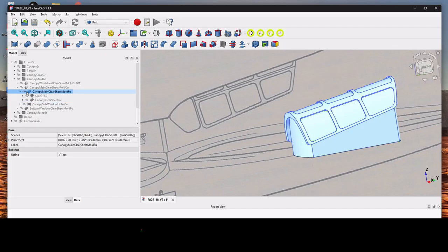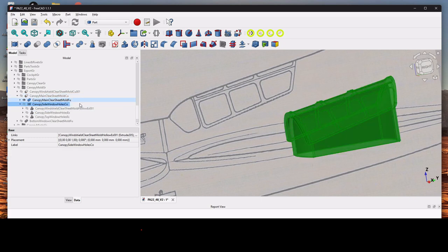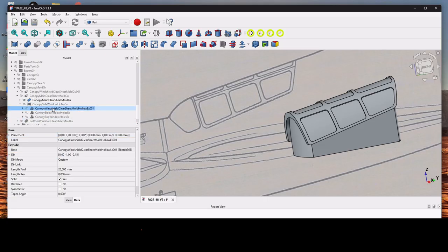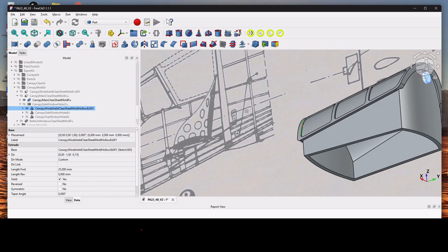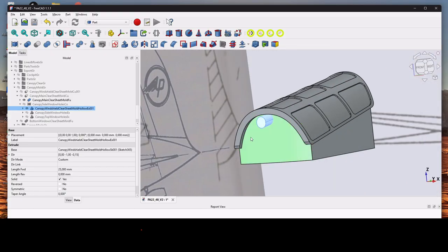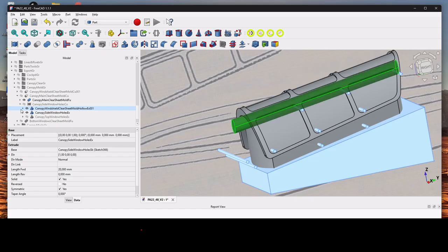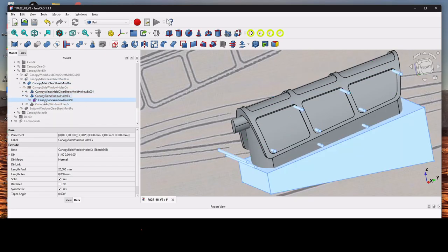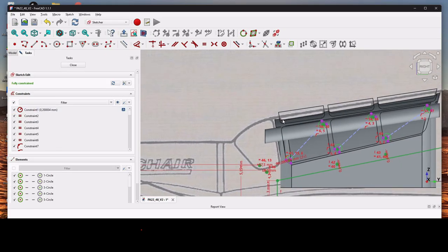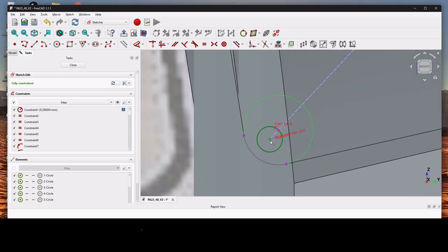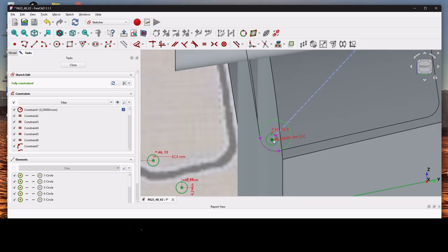As you've seen, what I've done is that I've gone a little bit further, and I've cut holes into my molds. So the first thing is that I'm using that in order to make sure that the resin will have a way to get out. Okay. And then I have my side holes here. My side holes, I've made several attempts in order to understand what are there. My side holes, they are something like that, and you can see here that the radius is 0.2 millimeters. So that means that the full hole has a diameter of 0.4 millimeter.